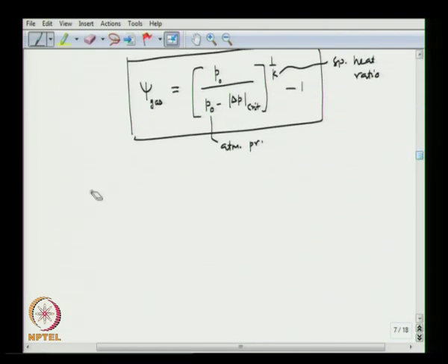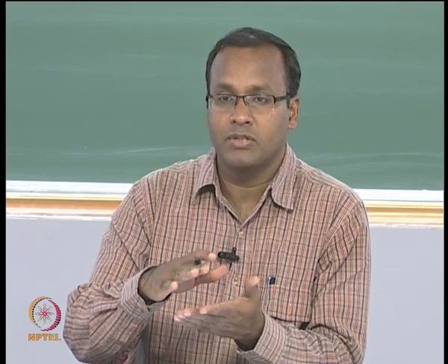Just to give you an example, we have a cantilever valve that has dimension 1700 by 1700 by 15 micron thickness. So, it is basically a cantilever plate that is getting actuated because of the inlet pressure. Normally the cantilever will close the valve port, and when the pressure exceeds, the valve port will open because of the deflection of the cantilever.